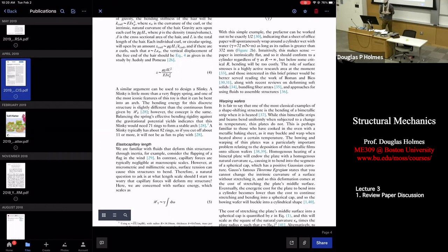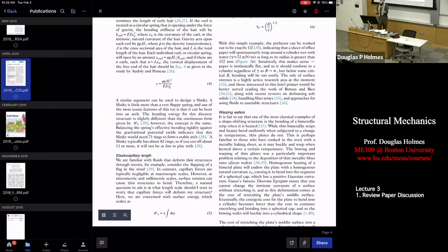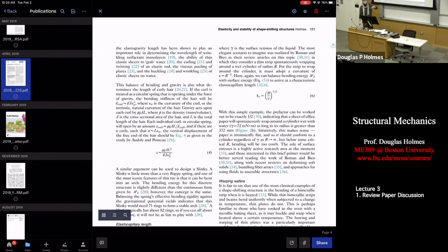And due to, I don't know if you remember van der Waals attractions from chemistry, due to van der Waals attractions, these things are really sticky. They adhere. And so for a while, people were trying to make these tiny pillars using photolithographic techniques. But what they kept finding was happening, I don't think I have a picture of it, was that as you dip them in the solvent, all the pillars would just collapse together, like your hair in the shower, or a paintbrush. And they're limited by this length scale here. They can only make them this tall before the fluid starts to pull them all together, coalesce, and then you can't make a tiny pillar anymore.